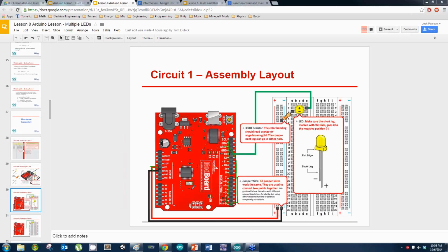All right. So from here on out, I do want you to connect your grounds like it's set up here. Like this ground is going from here to the breadboard, from here to here. So for any circuit that we hook up, go ahead and assume that is going to happen. That way, when I do label out how to plug things up, I'll just say plug your resistor into ground, which is going to be this row. Does that make sense to everybody? Does everybody capiche? Comprende? Understand?